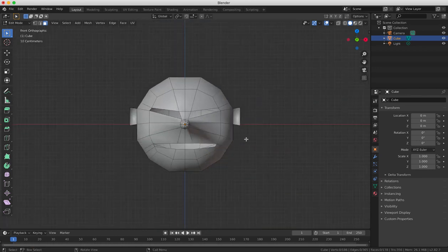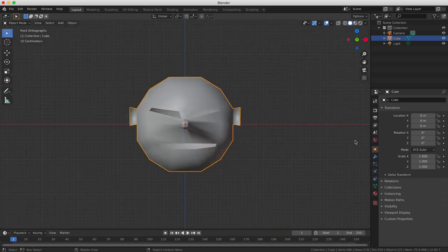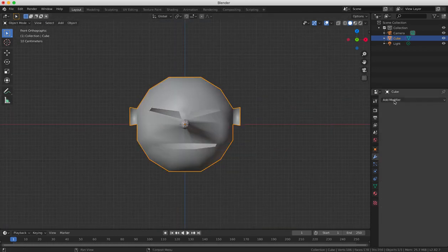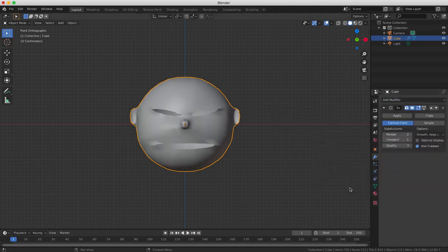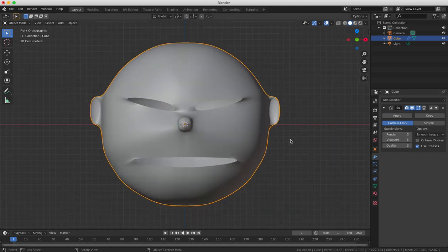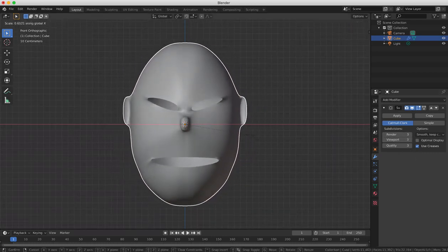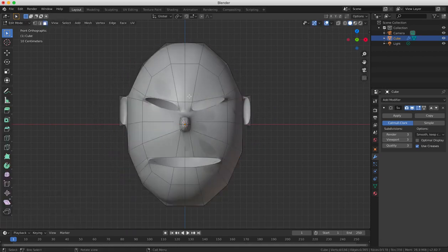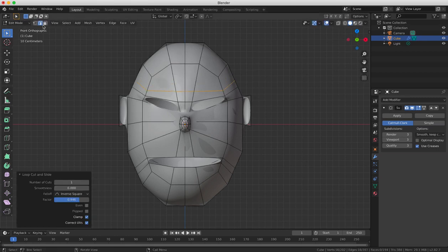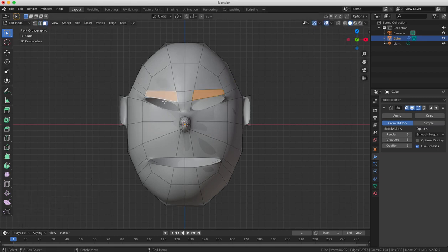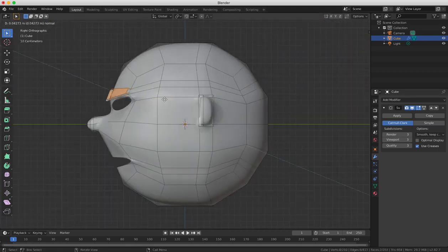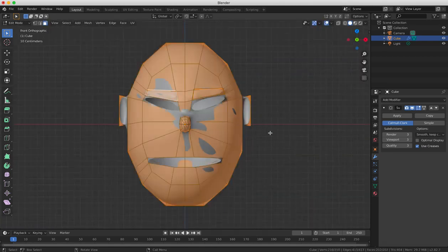Next, we're going to open the Object Modifiers tab in the Properties window. And next, select Subdivision Surface from the Object Modifier options to smooth out the cartoon face. This is known as a subsurface modifier, and Blender works out the mathematical equations to make the object appear smoother. You can increase the number of subdivisions, but generally it's not advisable to go above 2.